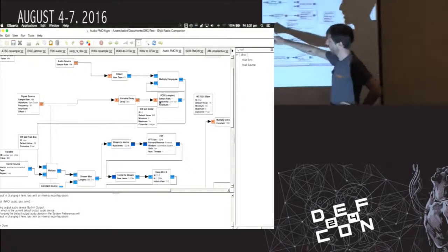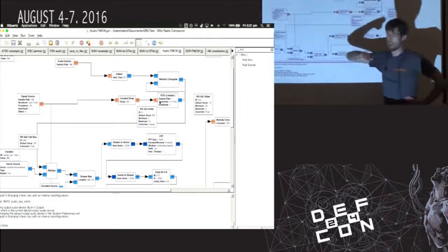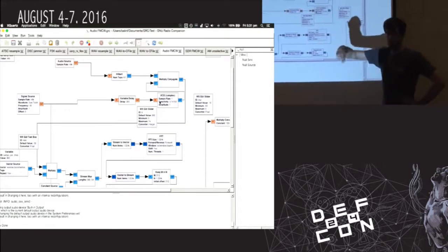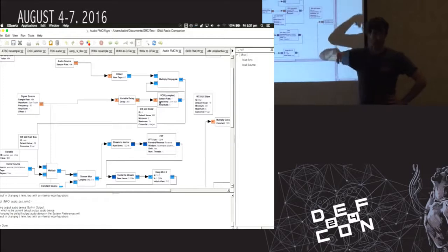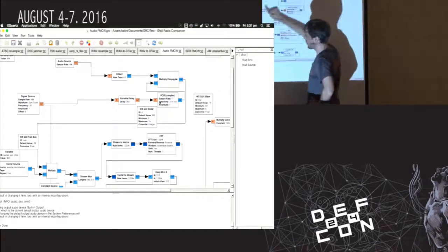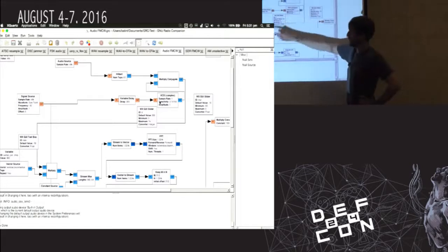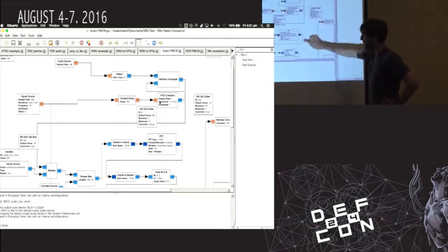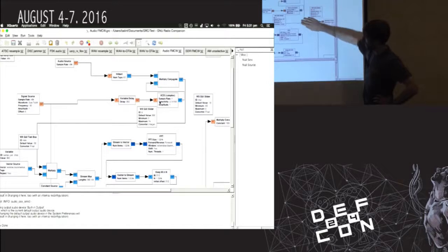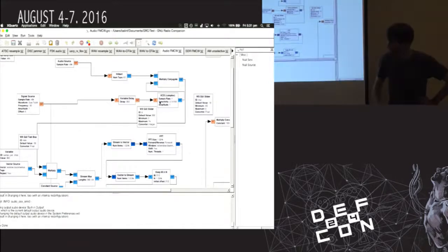So what you can think about is the sawtooth is controlling the frequency of the waveform that we want to generate, and the VCO is actually generating that waveform at the frequency. So this is constantly doing this sawtooth, and so our frequency is constantly going from low to high, and then low to high, and then low to high. So once we've generated the chirp, we mix that with our incoming signal, and then it goes off down there.